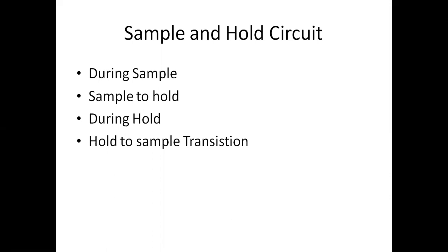While in the sample mode, the capacitor charges, where Q is equivalent to CV, which continuously changes in response to the input voltage. When the hold command is invoked, the switch opens, disconnecting input from output. This freezes the capacitor charge and hence the output voltage at the instant of switch opening. So the variation that provides improved low frequency tracking is commonly used in sample and hold.